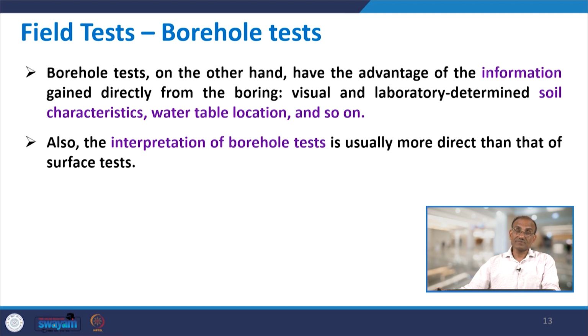Now, in the field test there are surface tests which are conducted from the surface, but there are some tests for which you require drilling and a borehole. Drilling a borehole may be expensive compared to when you do not require drilling, and it is laborious also. However, the good advantage of drilling is that you are able to collect samples from the soil which can be further tested in the laboratory.